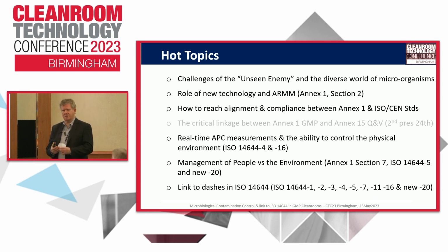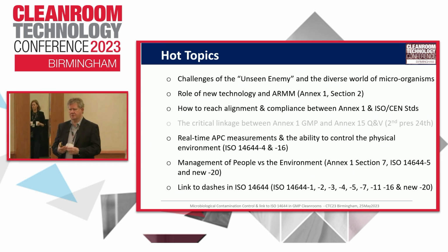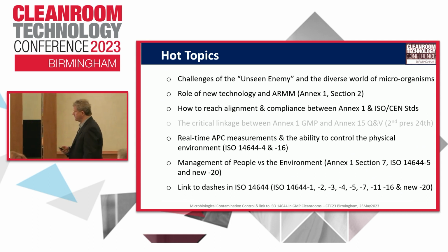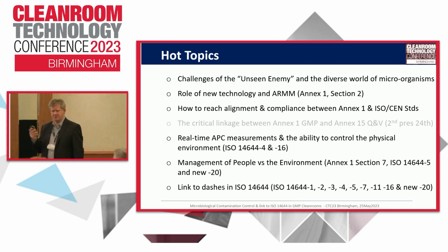I'm going to talk about some context around hospitals, where the patient in an OR is full of contamination, but it's their contamination. They don't want it from the surgeon or the nurses or the cleaners, right? The same way with food, it's about being orally ingested. We don't want to discover we can't go to work the following day because everyone gets sick. So there's a lot going on in that side of it, right? But it's really important to recognize as an overview that we can control the environment because we can measure it. We can measure total particles, we can measure pressures, temperatures, humidities, flow rates.